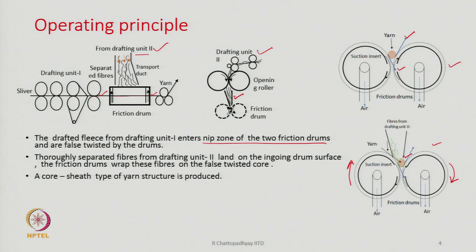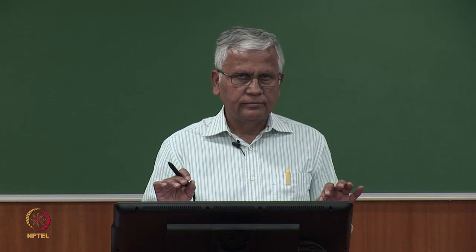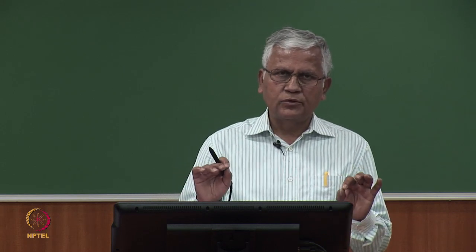Sometimes we see in the structure of the yarn that the core part has a little bit of twist still left, though ideally we expect no twist there, because the core is first twisted. But in practical cases, some twist remains, because by the time the twist is about to be removed, the sheath fibers are creating hindrance for the removal, and therefore some twist remains trapped.